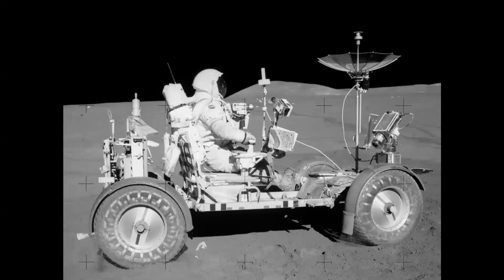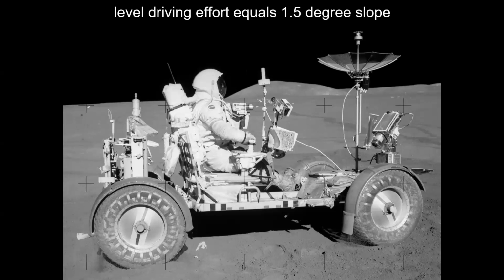As a wheeled vehicle travels on a level lunar surface, the energy consumed in overcoming the combined effect of surface roughness and rolling resistance, or soil compaction, is roughly equivalent to the energy expended in continuously climbing a smooth, rigid 1.5 degree slope. For the Apollo lunar roving vehicle, which carried 2 astronauts, the combined surface roughness and rolling resistance accounted for only 15% of the total energy expended. The remainder of the energy was lost to mechanical linkages, to inertia, to instrumentation, and so on.